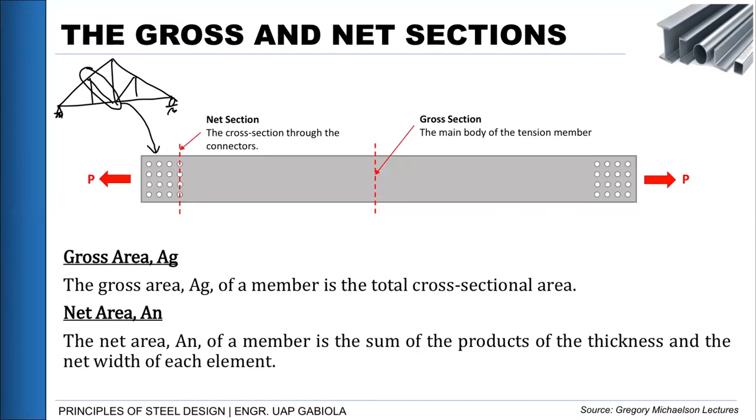So as you can see, the tension member looks like this on site. Then as you can see at the end of this member, we can see holes on it. Those holes are basically used to insert our bolt, to connect our member to another member in the truss that we construct. So, to connect it to our top chord and also to our bottom chord and also to the member in the middle. Okay? They're using a bolt connection, that's why our section has holes.